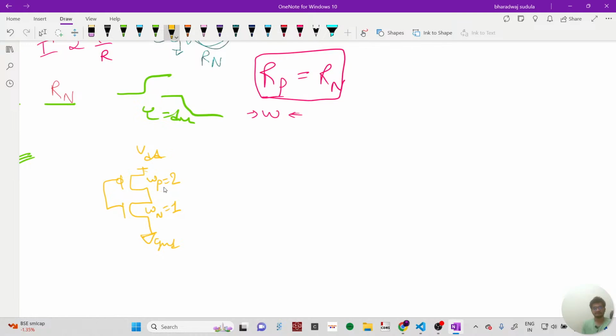So now this is the standard inverter, because we have considered everything that contributes to delay. Tau is RC. We have taken care of the capacitance. Capacitance is just a constant. It doesn't have any effect on rise time or fall time. It is constant for both cases. Resistance is the one that changes, so we have sized it accordingly.